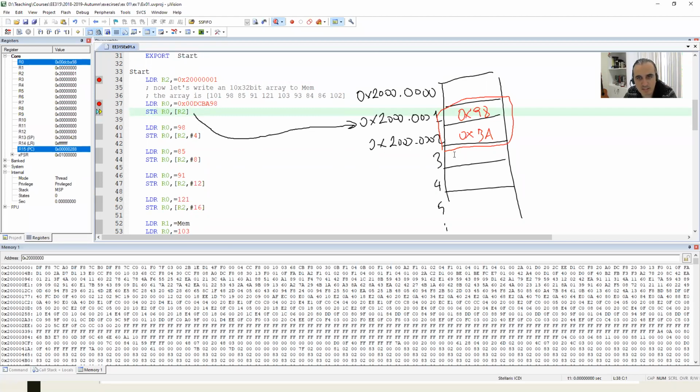This time this is STR, which means it is going to write 4 bytes, all these 4 bytes, starting with this location. So it's going to be DC and 00, all 4 bytes, because although you have 00s here, since STR is 32 bits, it's going to write them all to 4 bytes.